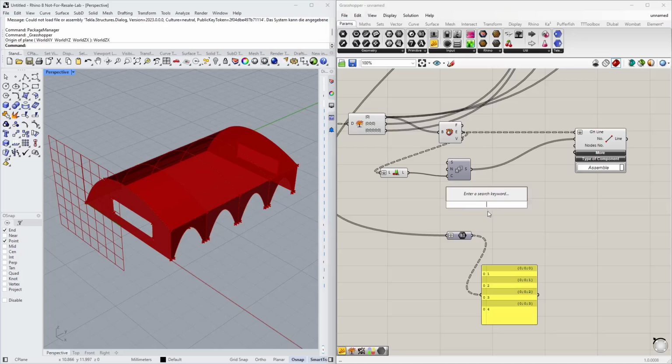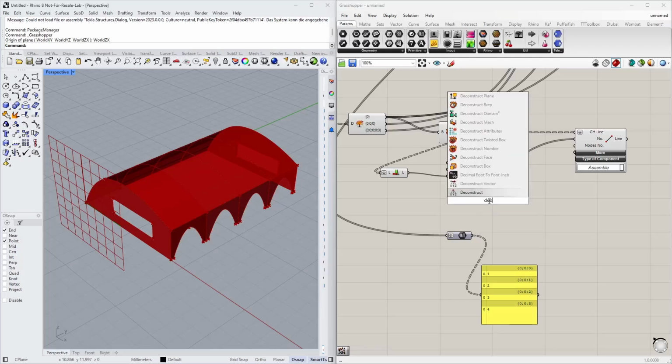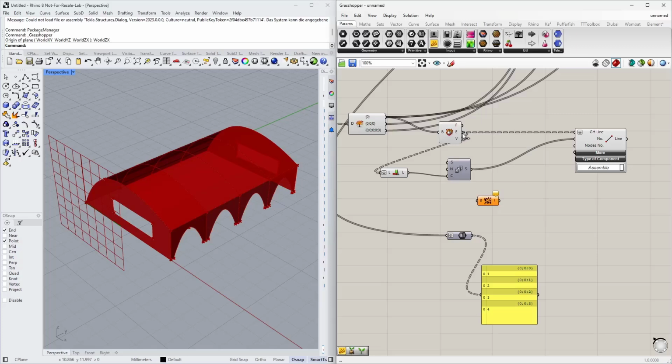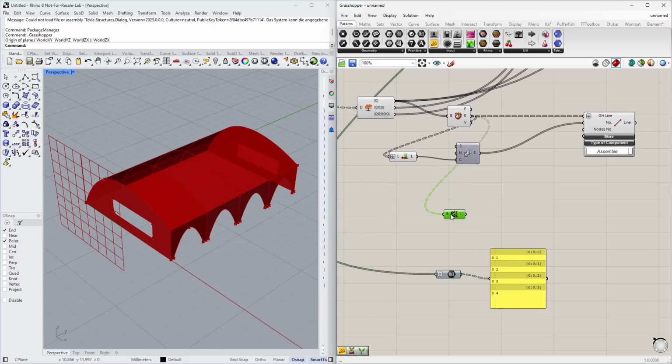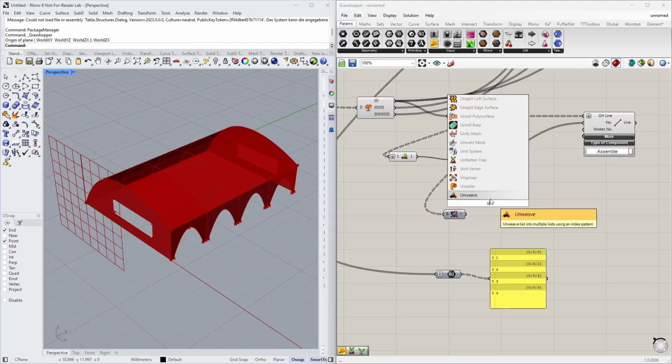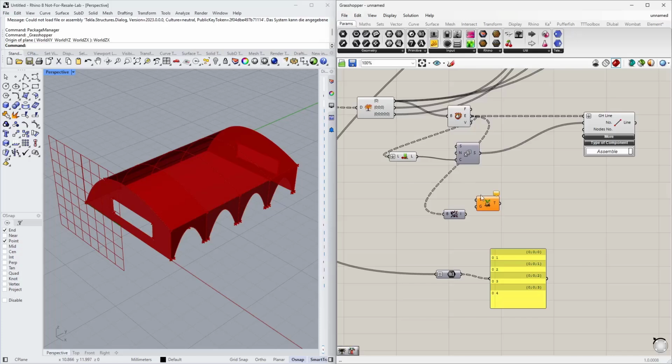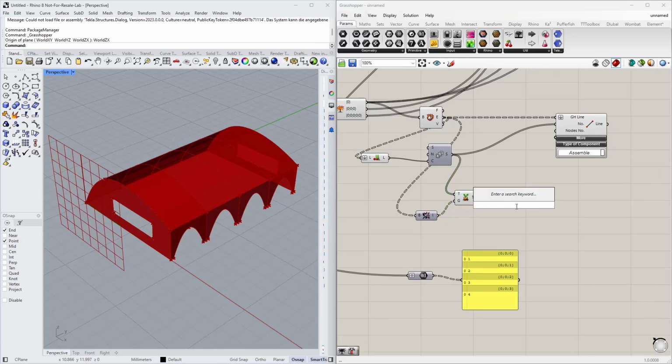And this grouping I would like to assign to my numbering here. How can I do it? I can deconstruct the path. Oh, wrong. Deconstruct path. I can deconstruct the path that I just showed here, where the lines are grouped. And then I can unflatten a tree from these numbers. And then I trim that tree. Trim tree.